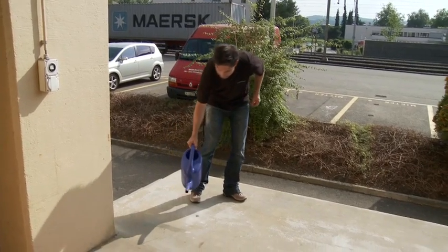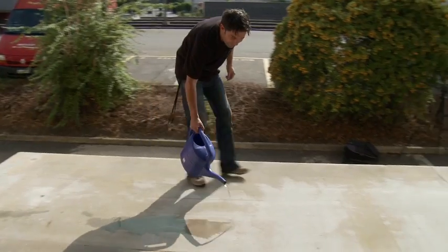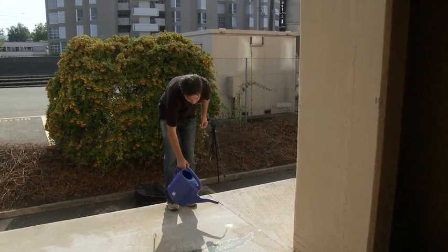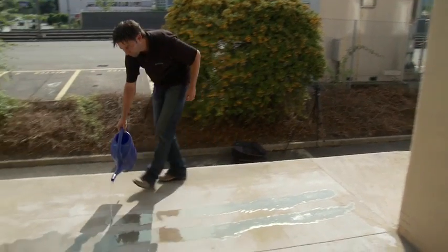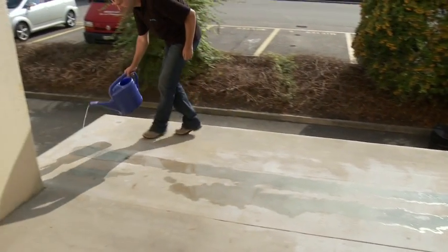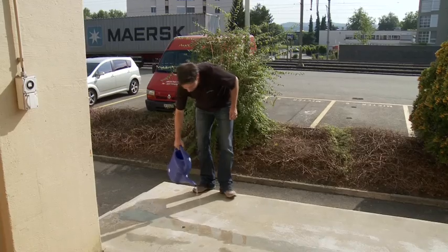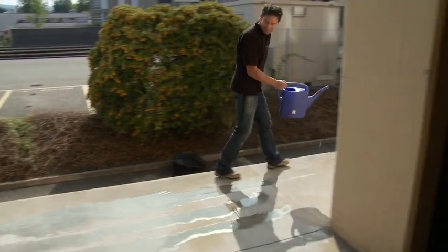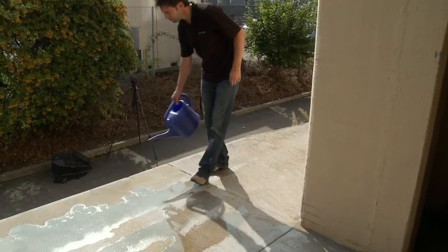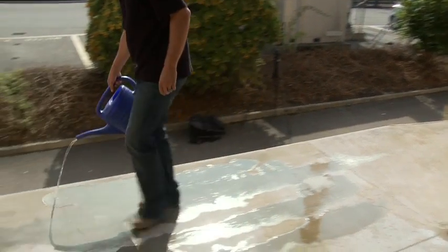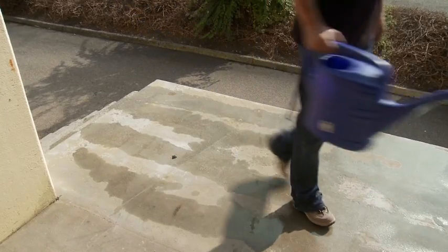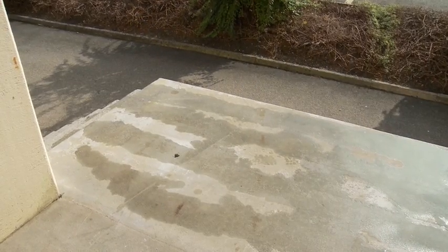The contact between the pore solution of the concrete and the probe can be impaired by a dried out concrete skin. This can greatly increase the electrical resistivity of the concrete. It is therefore recommended to moisten the surface approximately 10 to 20 minutes before carrying out the measurement. If this is not possible, it must be ensured that the sponge on the rod electrode or the felt hoops on the wheel electrode are sufficiently moistened. Now to carry out the measurement.